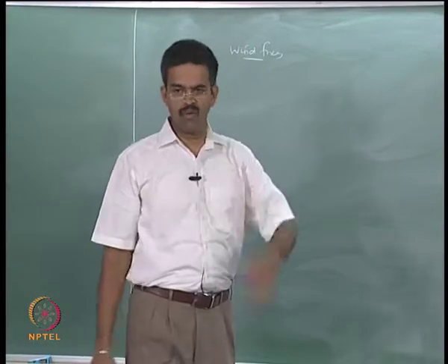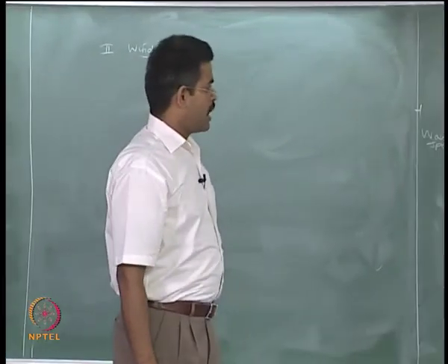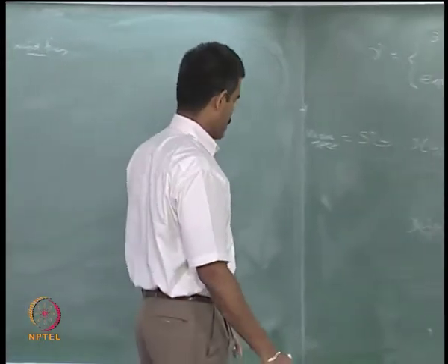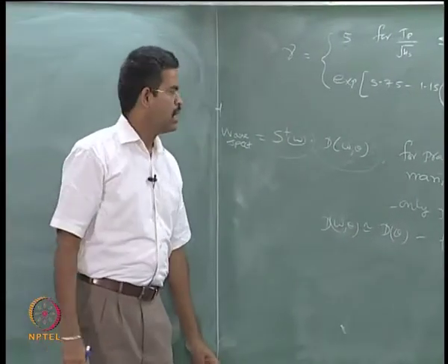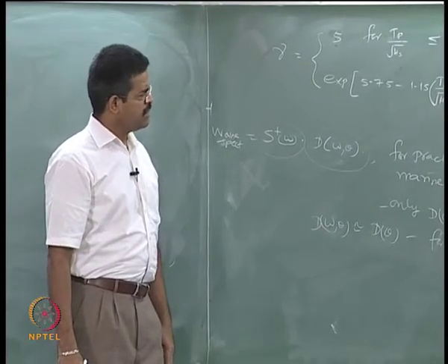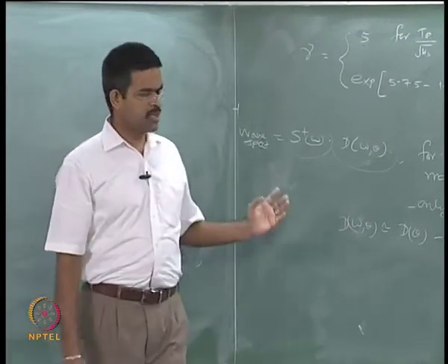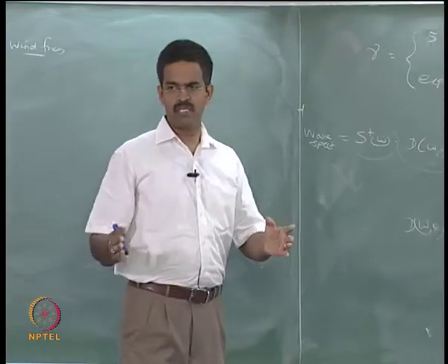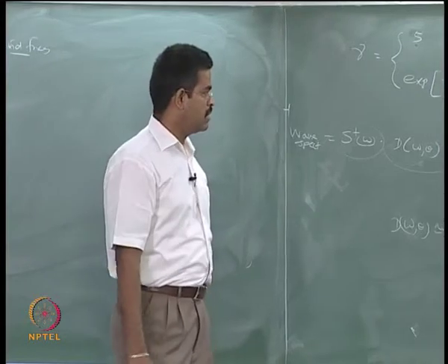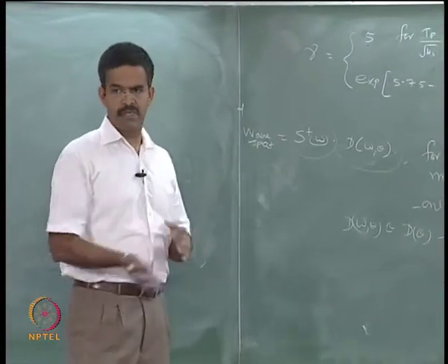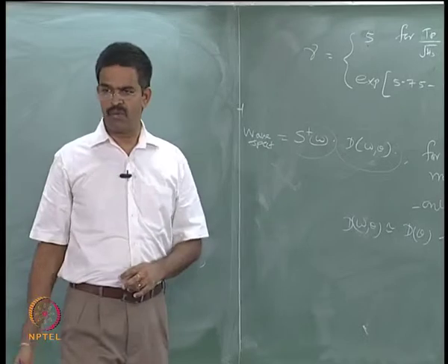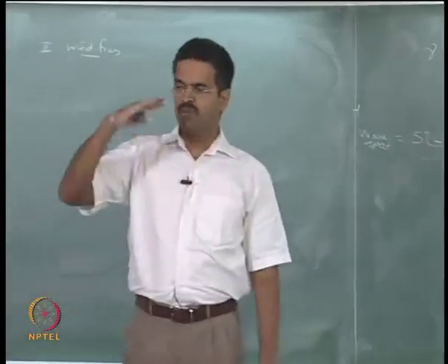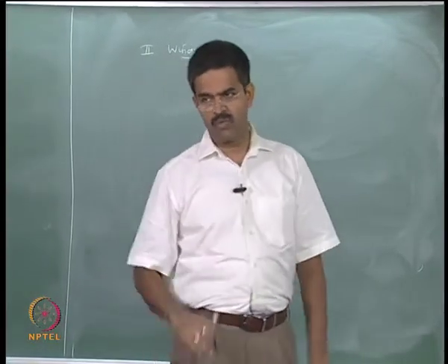We have discussed the wave loading, and we have seen what kinds of damping arise from the wave loading. Fundamentally we saw how the loading acts on the marine structure. Then we saw the water particle kinematics defined by the simplified Airy's theory, and the stretching modifications suggested by various researchers, which are implemented because Airy's form accepts values only till the MSL, whereas the variable submergence effect is not accounted for.